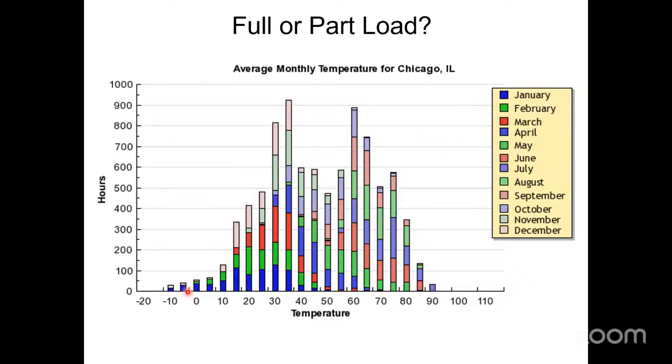So this is just a visual for you of how much time we spend heating and cooling in the Chicagoland area. This is bin hours. So if you didn't know, there's 8,760 hours in the year, and this graph represents all 8,000 plus of those hours at the same time in little 5-degree bands. So, here's 80 to 85, here's 85 to 90, here's 90 to 95, and this is how many hours you have. So hours that are 95 degrees of the whole entire year, we have like, I don't know, what do you want to call that?